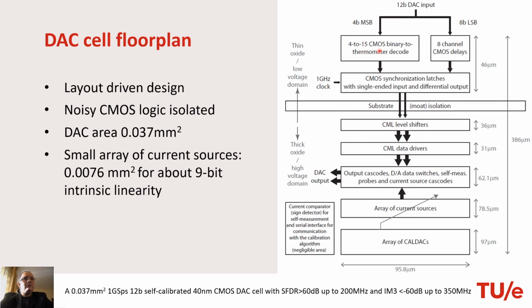Here the CMOS switching is very active, generating a lot of disturbance, while in the analog part we keep everything quiet and clean. For digital gates we use CML logic, for which only constant current is consumed, and we don't have switching of currents in the power supply.